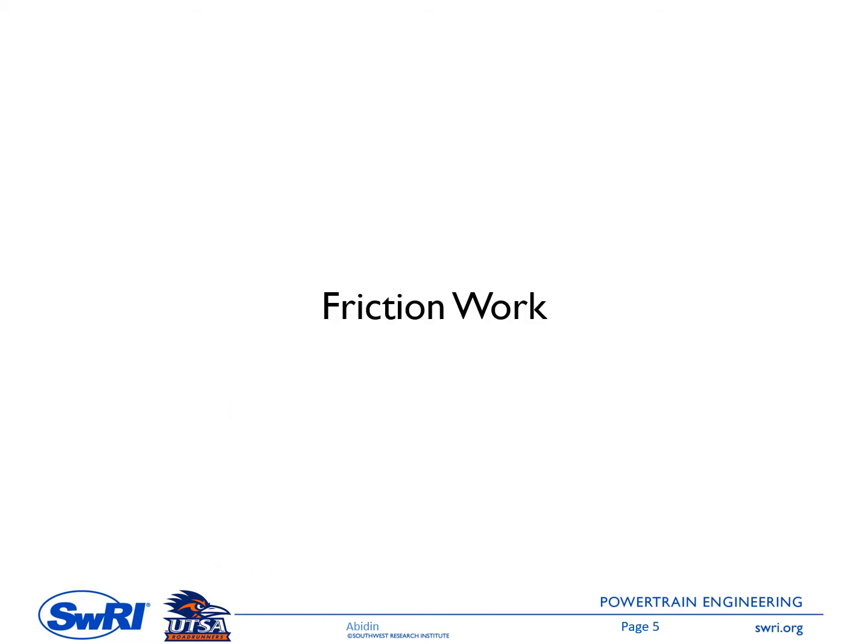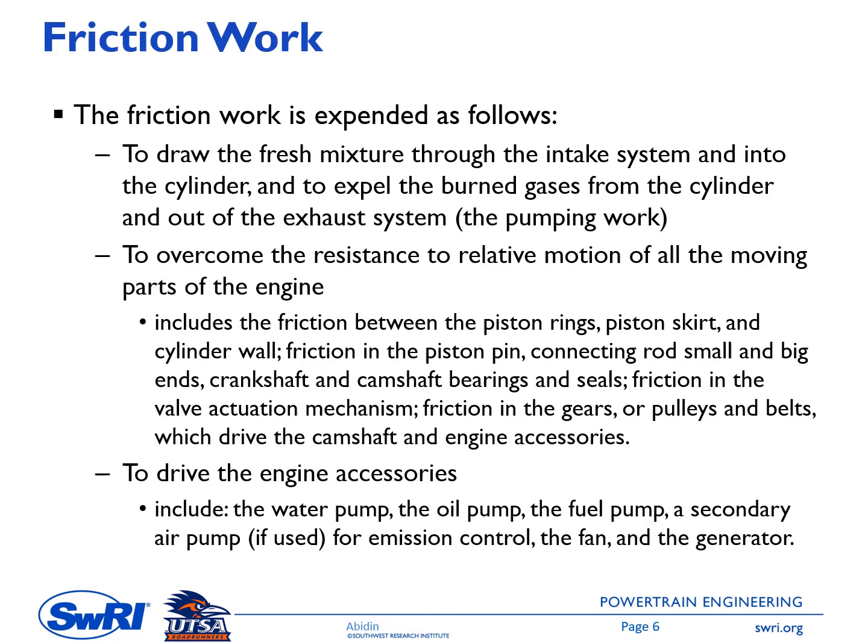Okay, let's take a look in more detail at this friction work. The friction work is expanded into the following items. First is to draw the fresh mixture through the intake system and into the cylinder, and then to expel the burned gases from the cylinder and out of the exhaust system. And such friction work is called the pumping work.